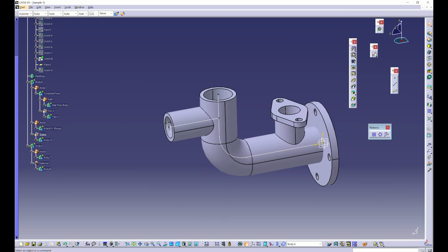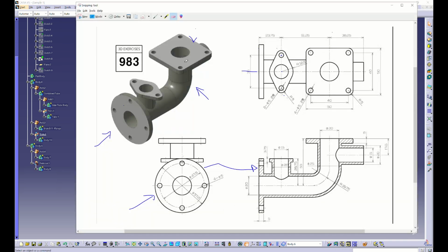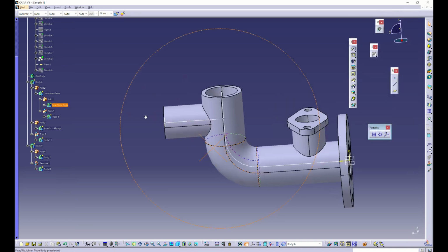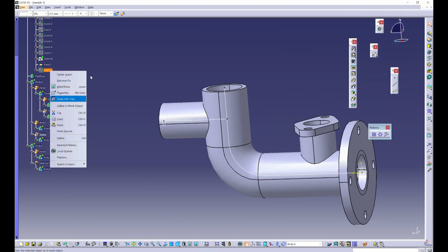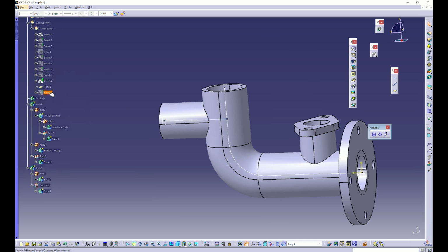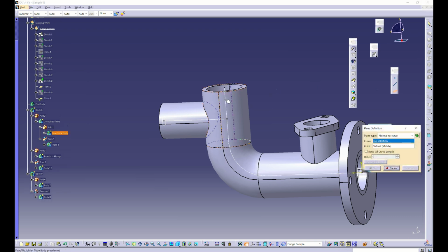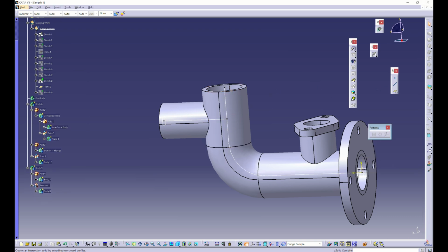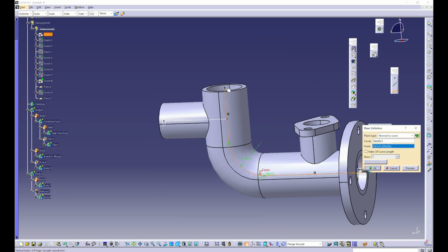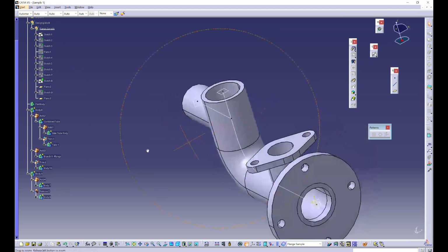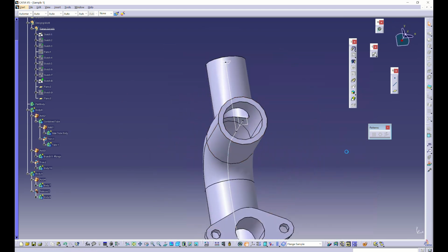And then next is the rectangular flange above. Since this one is the one also, let's create another reference plane using this guide curve. Oh no, click, then click this. Okay, we have now a reference plane.